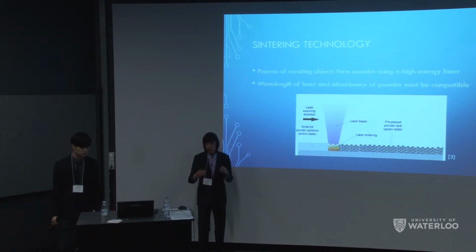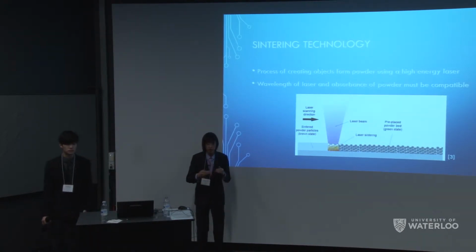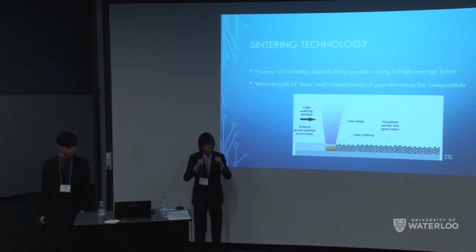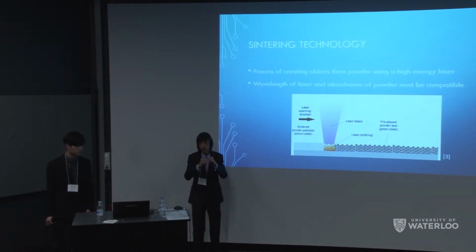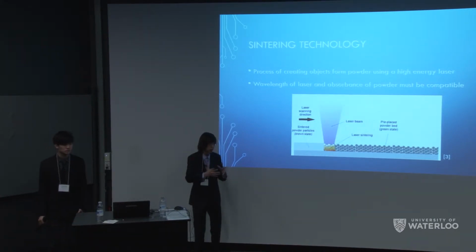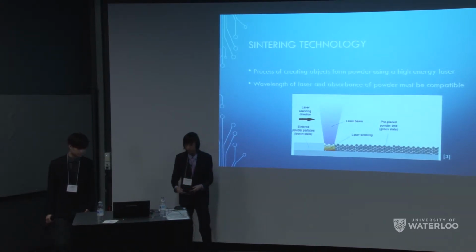Melting is when you physically change it from a solid to a liquid phase, while sintering is more about promoting diffusion between the atomic boundaries and the grain boundaries in order to make what's called a solid mass. If you think about two or three ice cubes in a glass of water that combine into one ice cube, that's more closely aligned to a sintering process.